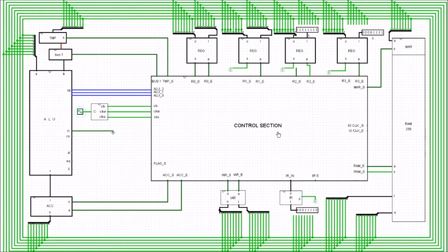So what we've done is we've enabled the value here onto the bus, which is all ones, and then we're going to put that value into the RAM set, and it'll go into the memory location given by this here. So if I was to drop into it, we'll just go over the next clock pulse to set it going low now.